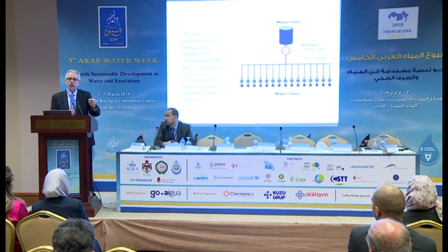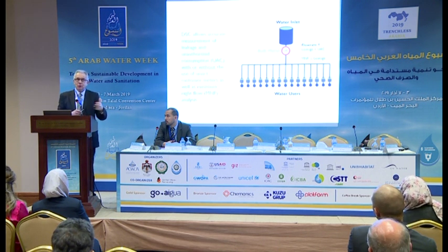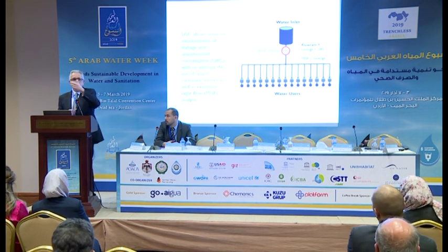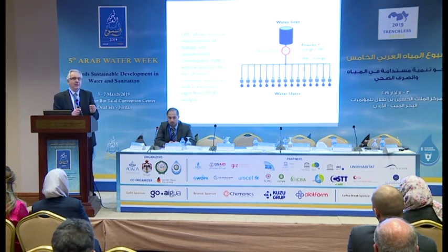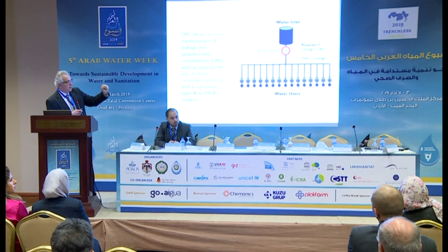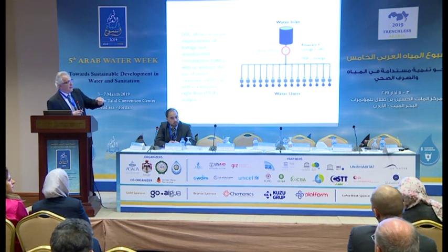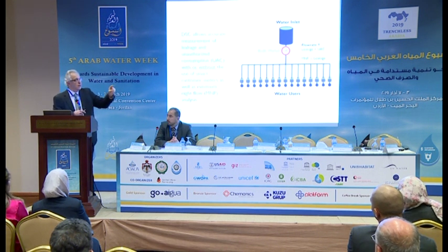What next? We meter the water going in because we have continuous supply. So we can have a nice graph, and we'll be able to analyze the minimum night flow. Again, we can see here on the right-hand side, flow rates. When the valves are closed, you can see the valves all closed, being of black color, it's leakage plus unauthorized consumption.